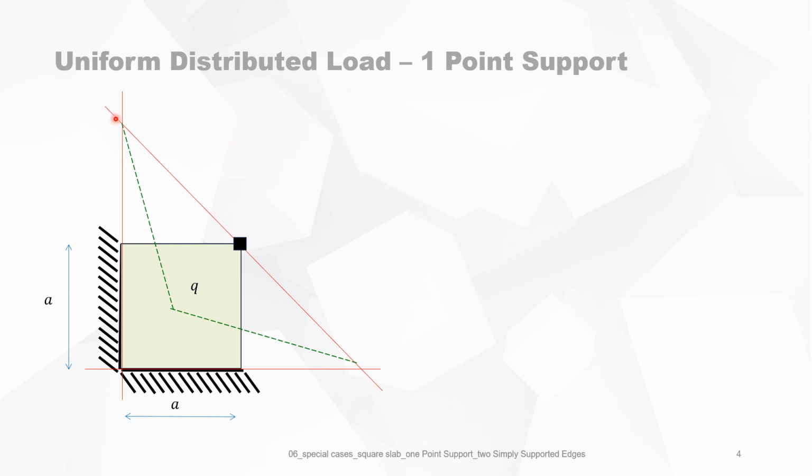The yield lines start at the intersection of two rotation axes with a certain angle, which is alpha, the same here. This angle is the same as this angle because of the symmetry. And this is the third line, but this angle is known because it is 45 degrees because of the symmetry around this axis.